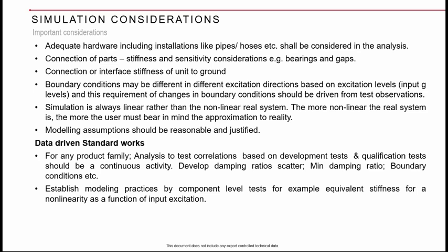When you go for development test, you will not see much gap between your analysis and the test if you adopt that, and then you can skip the development test route that you have to adopt for uncertainties, because this indicates that you have embraced all your uncertainties and now you are good to go directly with qualification tests.